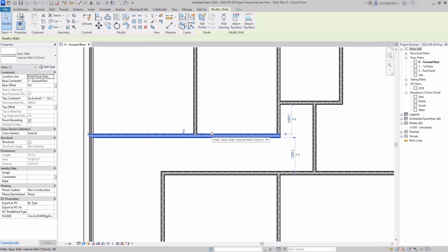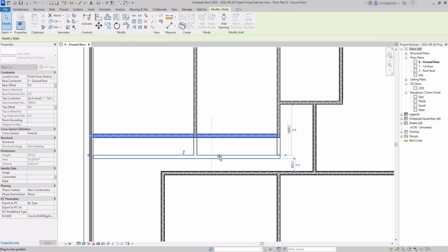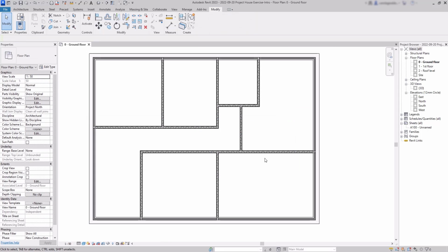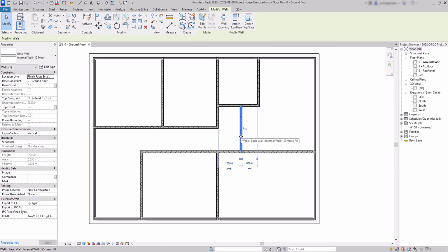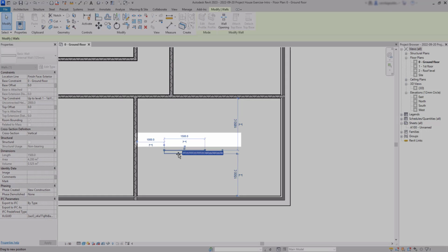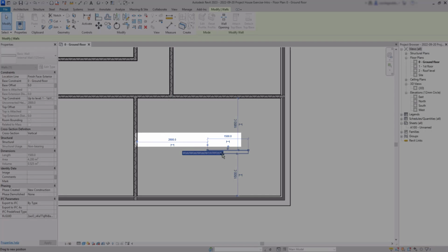If you select a wall and try to drag it, click and hold and move, we can only displace it in a way that we won't deform the structure, in this case up or down. Because if you try to move it in the same direction, Revit doesn't let you, because it's constrained with the vertical walls. That's why if a wall is vertical, we move to the left or to the right. However, if a wall is isolated, it has no constraints, you may have temporary dimensions along the same direction.